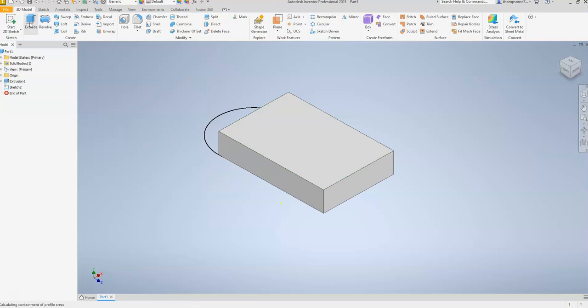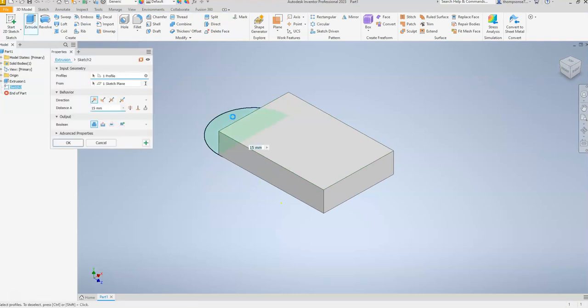And now I'm going to extrude this rounded feature. I'm going to select this, but unfortunately it's only going to give me one, so I've got to select both of those. All right, so it's going downward. We do want to join, so this is correct, but I want it to go upward. Still a join. All right, and this rounded feature will go above the rectangular feature. So we're going to extrude this by 40 millimeters. So it's going to stick up just like that. And say okay.